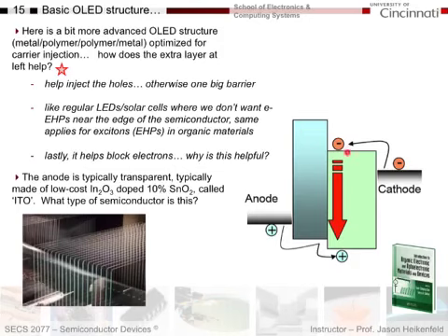So, first thing, here's the light emitting layer here. Here's my cathode, which injects electrons. The metal, you can see, is closer to the conduction band here, so it will inject electrons onto here. So I get my electrons here waiting to recombine. My anode is a metal with a work function that's way down here compared to the cathode. And so it lines up down here and it's able to inject holes, which can make it here and recombine with electrons.